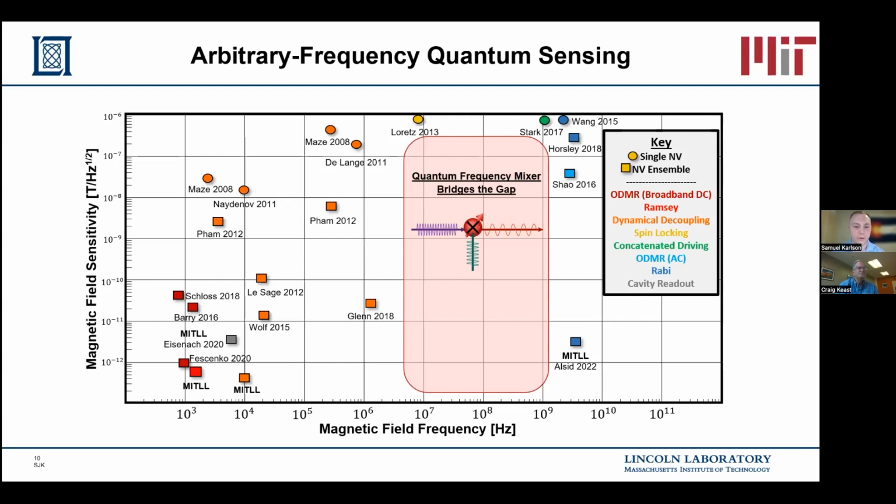For the spiral images, we're normally about 60 microns away. If you are much farther, say 100 or 200 microns away, you're better off using a different sensing technique like superconducting quantum interference devices, SQUIDs, or something else, because one of the advantages of those systems is that you can be further away. For this technique, you want to be as close as you can to the diamond.